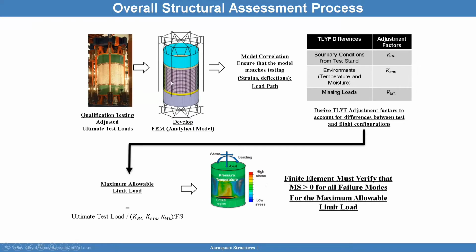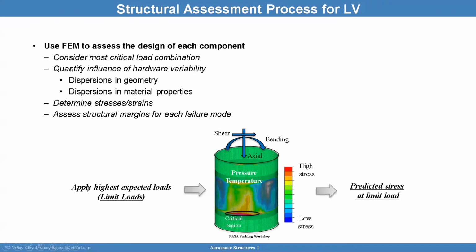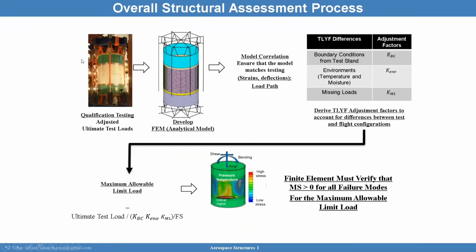You also want to make sure that you create a finite element model that's actually quite fine, a good fine mesh for the flight configuration. So not just for the test configuration, for the flight configuration as well, because you're going to have some flight load cases that you may want to make sure that you then compare against the test configuration. The test configuration, I apologize for that.